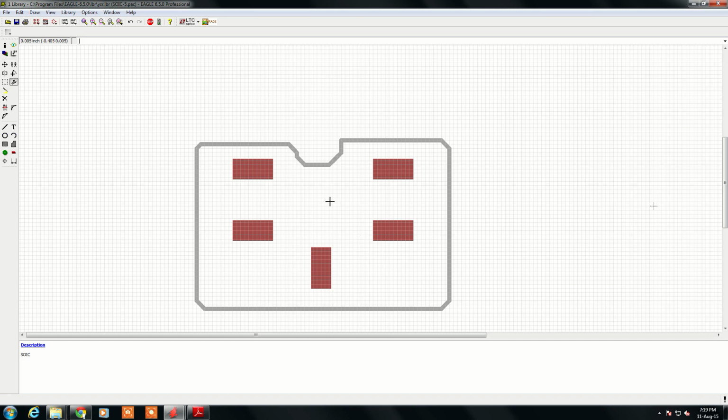Now while doing that, I repeat again, the placement is very important. You should know which is pin number 1, which is pin number 2, 3, 4 and 5. The orientation is important, the starting point is important, distance is important, width and length is important. And whether this IC is an SMD IC or a DIP. In DIP, the pads will be like this. You can use a square pad or a round pad or an oval type, whatever. So there is a difference.